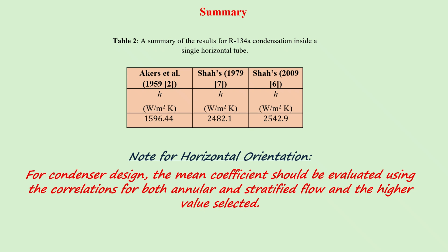We may get these values depending on the correlations available, and then we compare them and use the higher value to estimate the overall heat transfer coefficient of that condenser. Please go to these references and see how you can improve your knowledge about heat transfer and condensation in these applications.